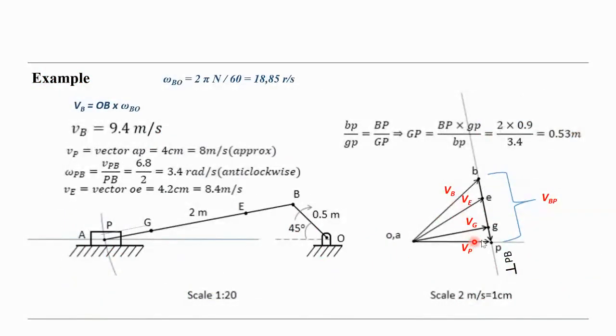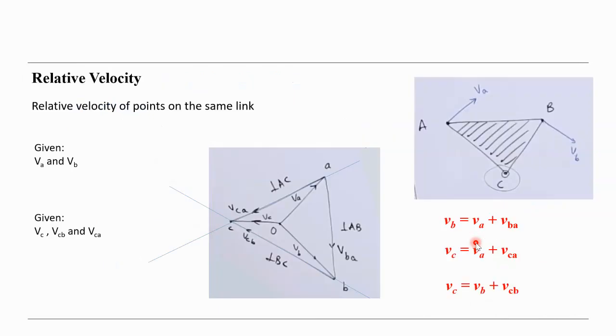So therefore let's assume that this is the smallest relative velocity here, and if we indicate the G somewhere here and draw this vector, we can calculate the VG from this graphic using the scale, and also we can calculate the relative velocity here, VG about the point P. Okay, this is the graphical way how we calculate the relative velocity.